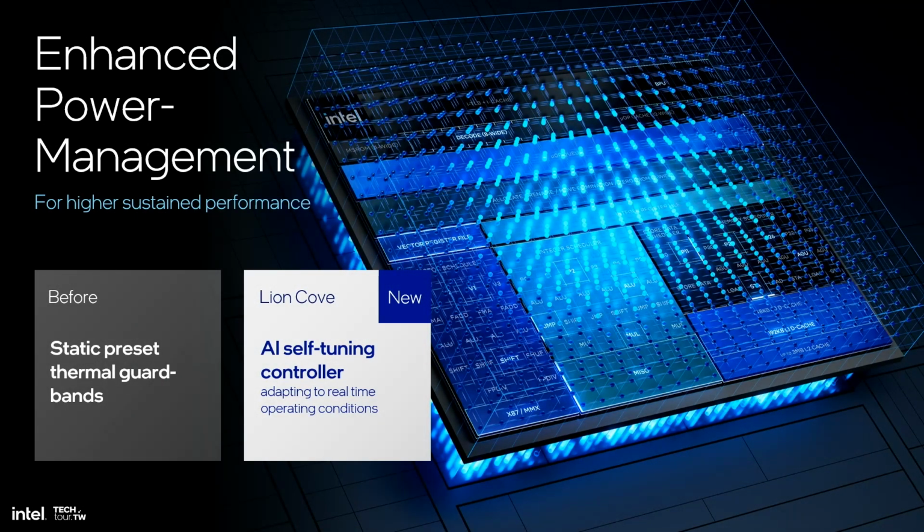Now, as we add performance to our CPUs, while aided by Moore's law shrink their area, we are faced with an increasing thermal density challenge. We must closely monitor the temperature in all places on the CPU and take immediate action when there's a chance of overheating. This is usually done by either throttling frequency or scaling back voltage.